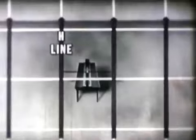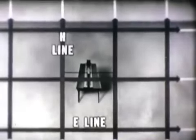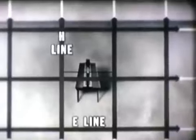Yet the magnetic and voltage lines retain a fixed relation to each other and to the Earth. For instance, stopping the wave, we see that the magnetic or H lines are still perpendicular to the voltage or E lines. Also, we see that the E lines in this wavefront remain horizontal or parallel to the Earth's surface. Because of the direction of the E lines, we say that this wavefront is horizontally polarized.